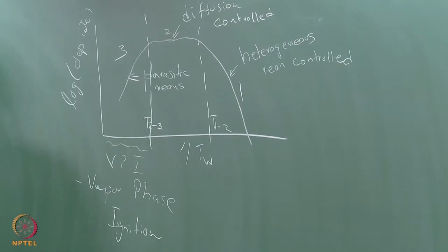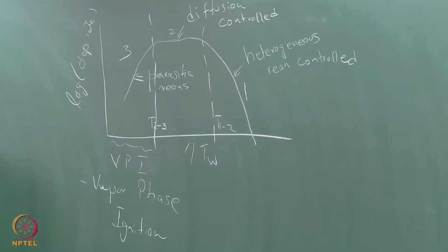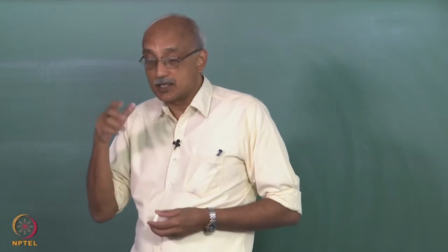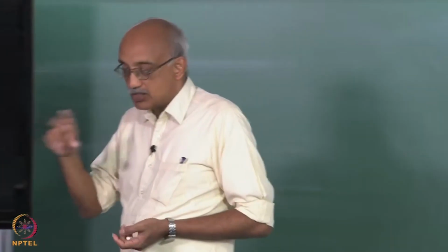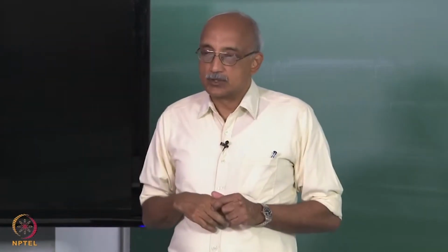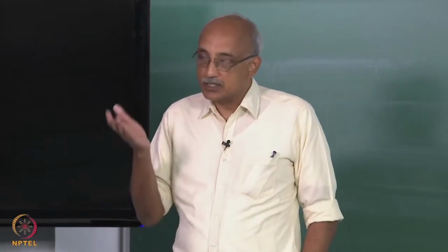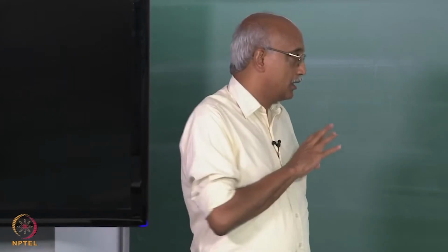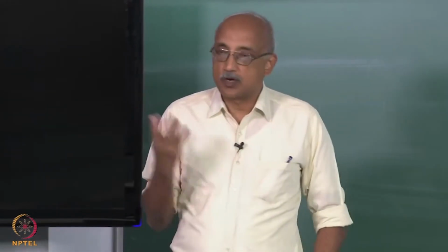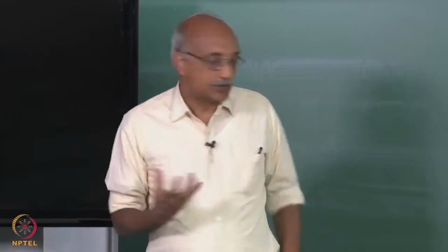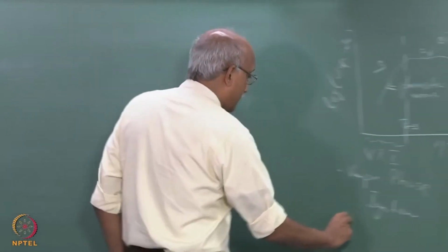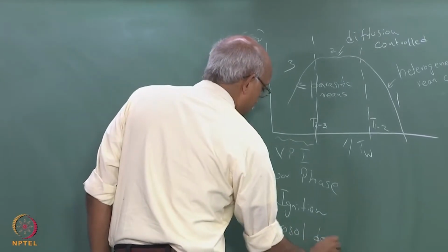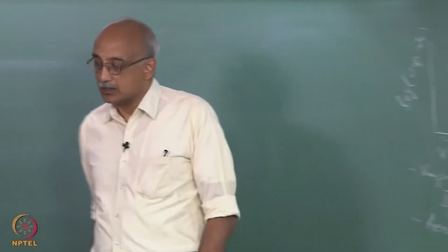Because essentially that is what is happening, the vapor phase is getting ignited, reactions are now starting to take place, and because the substrate temperature is so high, the adjoining gas temperatures also increase, so that even in the diffusion sublayer the temperatures become high enough that there are significant chemical reactions that start taking place in the gas phase itself, possibly leading to the formation of solid particles. So, this is also the regime where aerosol deposition or aerosol formation and deposition can be initiated.